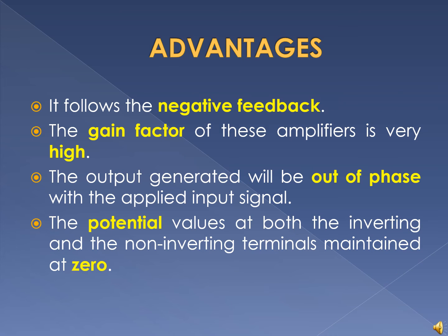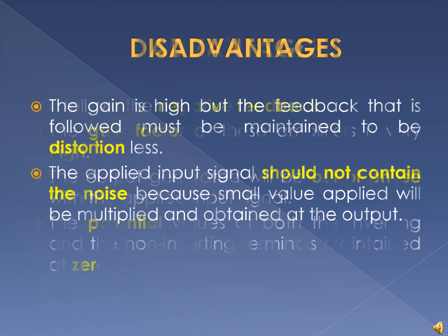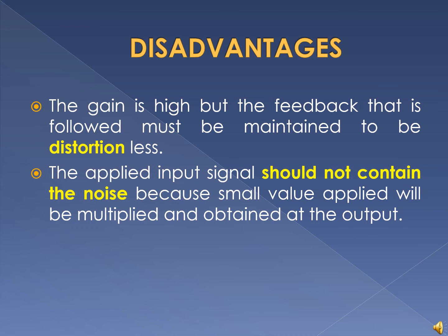Advantages: it allows negative feedback. The gain factor is huge. The output will be out of phase with respect to the input. The potential values across the inverting and non-inverting terminals are maintained at 0. Drawbacks: noises could affect the signal, and there are high chances of distortion.